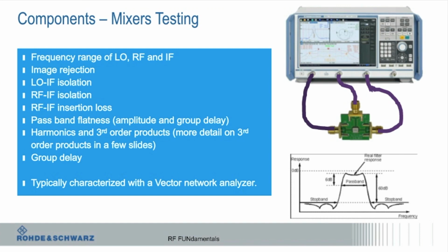So basically, signals bleed through that you don't particularly want to get there, and you have to be aware of those. The challenge when you design with mixers is you get lots of frequencies out. Typically you'll say IF is RF minus LO. Boom, I'm done, everything's good. The unfortunate reality is that's not all you get. IF is also RF plus LO. You get 2RF minus LO, RF minus 2LO, and so on. All the integer multiples of all those things will show up.